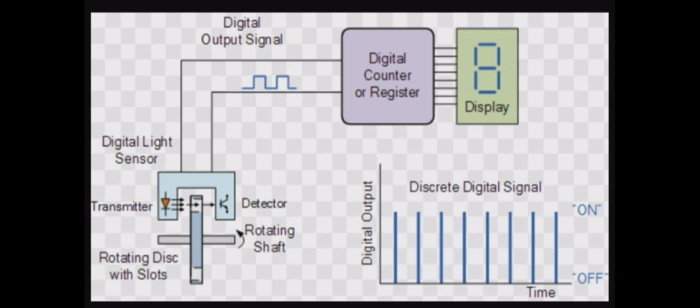By using one PLC output, we get a minimum of 2 or a maximum of 4 and above relay outputs. So only one triggering signal is required from the PLC, and we can get a minimum of 2 or a maximum of 4 to 6 outputs in the form of relays.